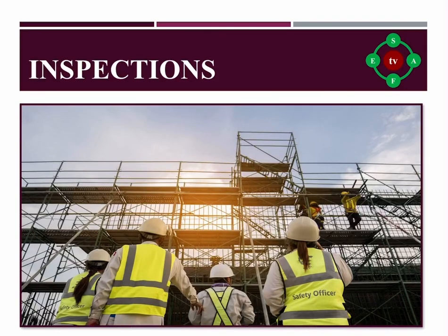Inspections. It is required that a visual inspection be conducted by a competent person before the start of every shift and after conducting work. Identifying defects through regular inspections can help minimize and eliminate hazards that can affect the structural integrity of the scaffolding and threaten the safety of the worker and the workplace.